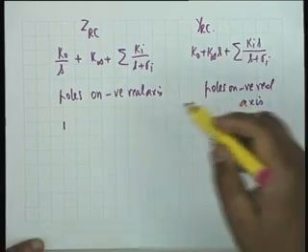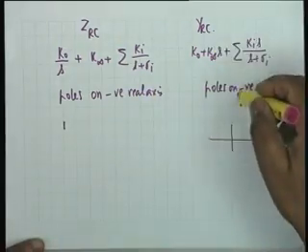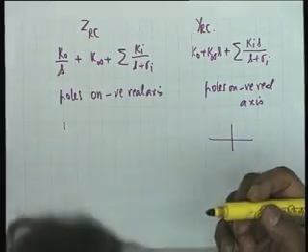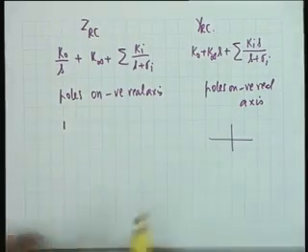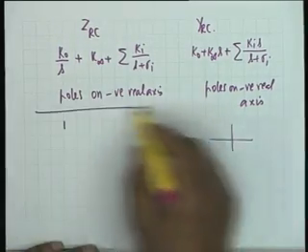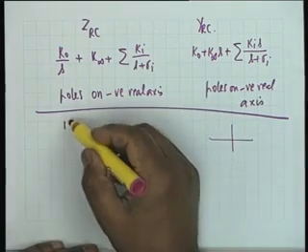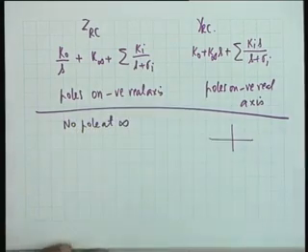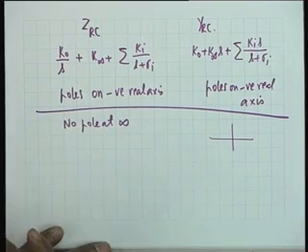What we said was, what are poles of YRC are the zeros of ZRC. So we conclude that poles and zeros of RC admittances all lie on the negative real axis. Then the situation at infinity, there is no way that ZRC can have a pole at infinity, no pole at infinity. Pole at infinity is not permitted, all right.